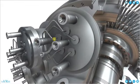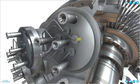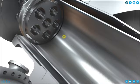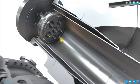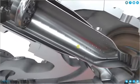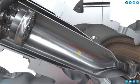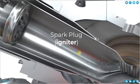You can see the fuel lines coming along here, along here, and along here, and the two on the bottom. And that fuel then is going to be sprayed and discharged into the combustion space. Initially, we're going to need to have a spark in order to ignite the fuel, but once the gas turbine is up to speed, typically beyond 50%, the temperature of the air is enough that we can keep combustion constant and we don't need any external ignition source, for example from a spark plug or similar.